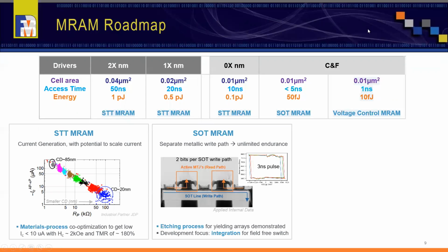SOT-MRAM has advantage of decoupling the endurance and the write performance. By using separate write path, we can achieve less than 5 nanosecond access without compromising endurance.